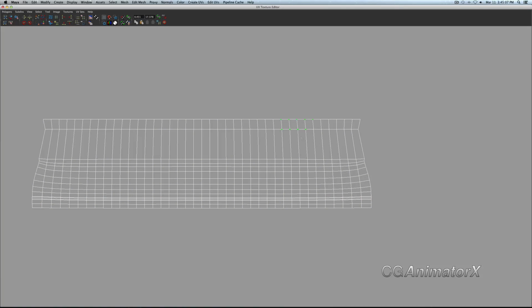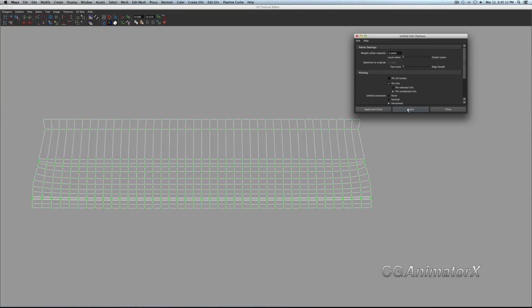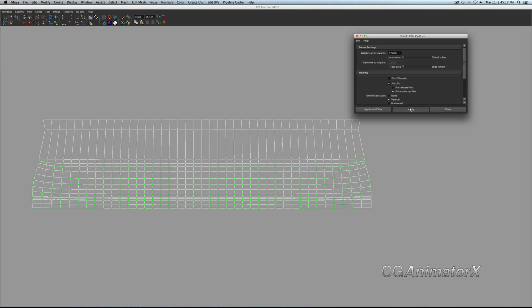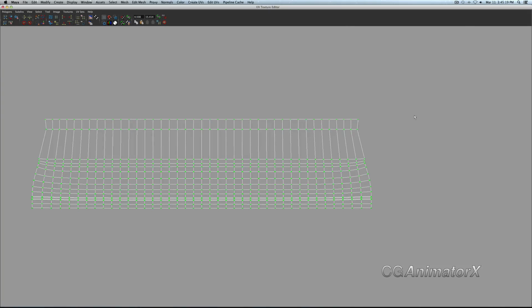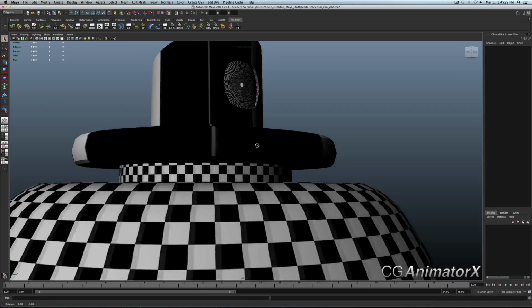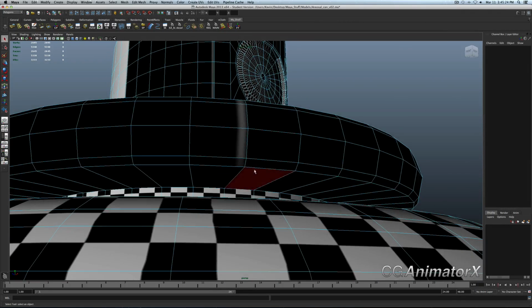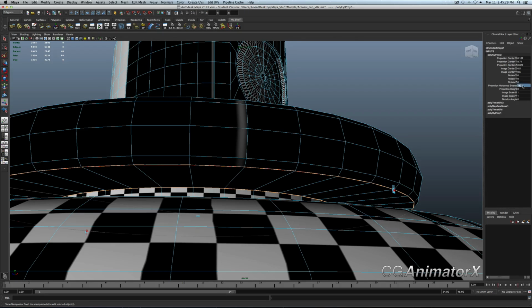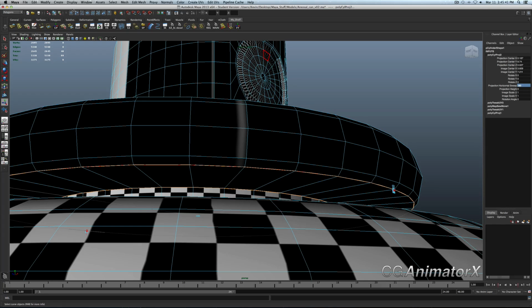Okay, select all the UVs to shell, unfold, horizontal, straightens it out, vertical doesn't do it justice, so we're just going to do horizontal. Okay, and now we have to select these faces underneath. I know this seems like it's taking forever with this process. Oops, 180. Keep that to 180, I forgot.